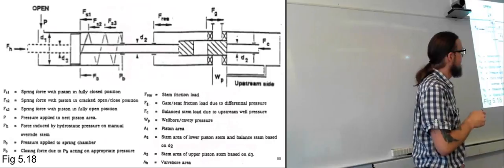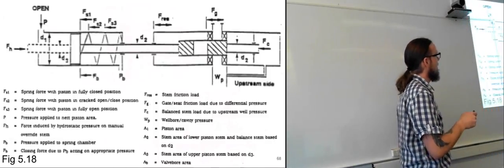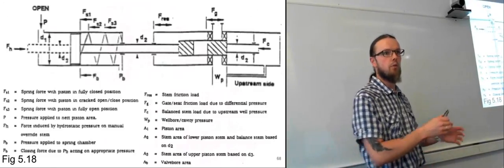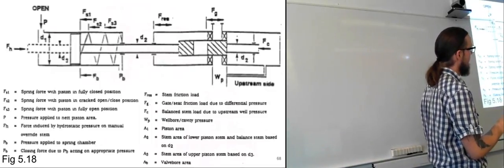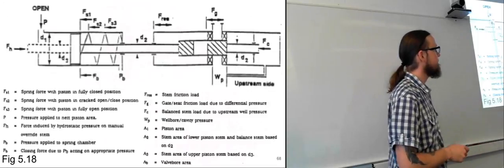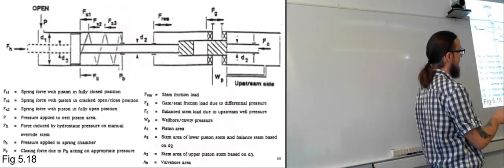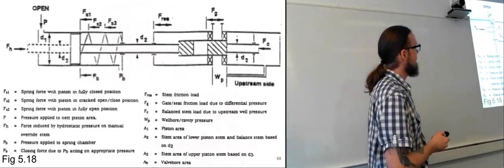So again, we have a gate valve here. We have the hydraulic part on this side. You can see the spring has been drawn in here. It's the fail-safe spring, the one that will close it if it loses the hydraulic pressure. And over here we have the gate itself in the valve, and here is the production line going through. So we need to move this opening over here so that we get the flow through it in order to get it open.